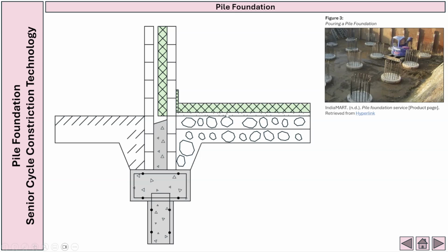On top of our 40 blinding, we've got 100 insulation, and then on top of that we have our 150 concrete subfloor. On top of this we have our 25 flooring, and then on the inside of the dwelling we have got our 12 render, and we have our 18 render on the exterior of the building.